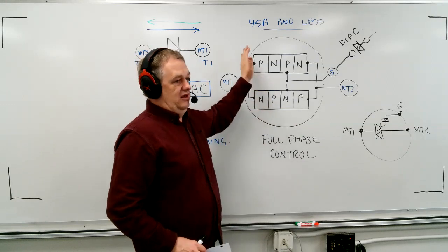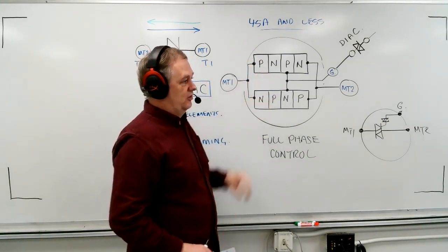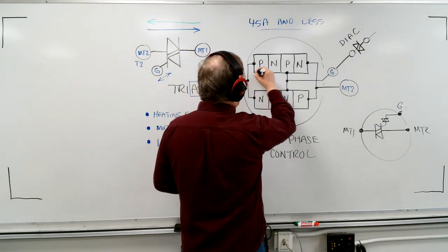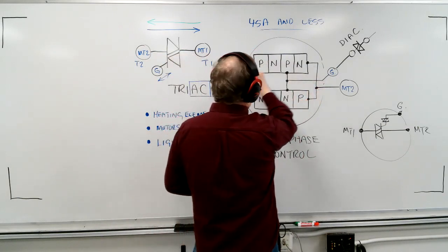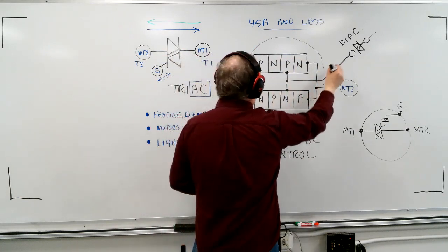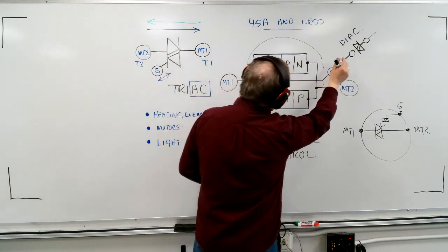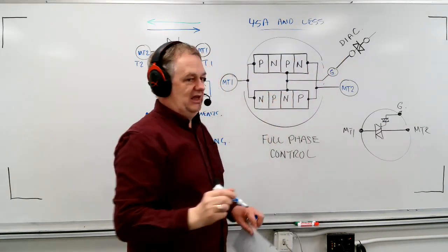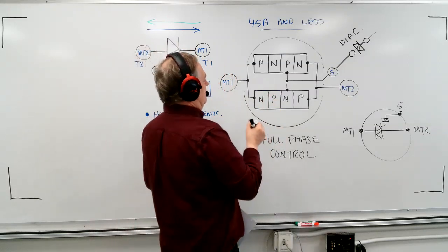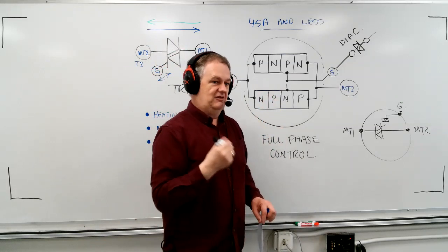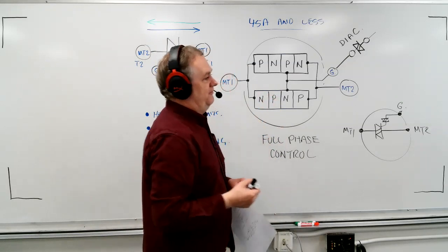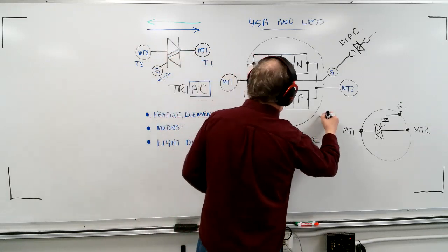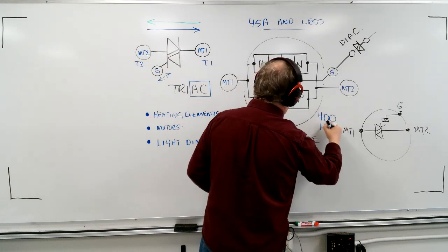The frequency that you can use this in, the frequency of control, is not very high. The reason is that as the currents move through, at one point they're going this way, then they're coming this way, and the gate current is coming in at one point and then going out at the other point. In the actual layers, the way the current moves is pretty sophisticated. If you start trying to press them too hard to switch too quickly, the phase control kind of breaks down and they don't work anymore. And so they are limited, and I'm just going to write this here, to about 400 hertz.